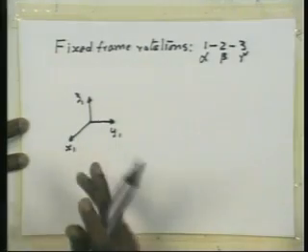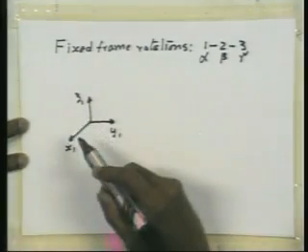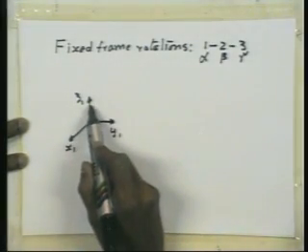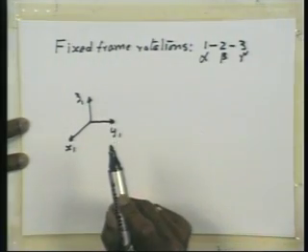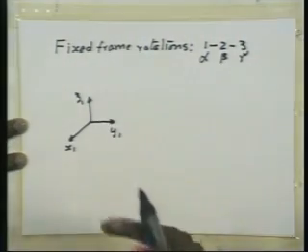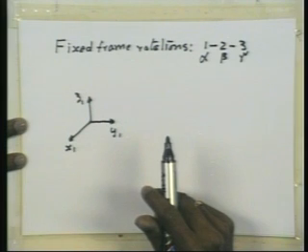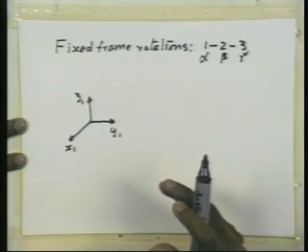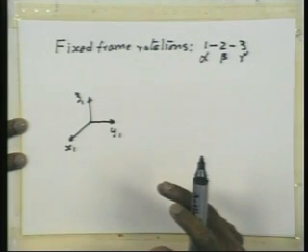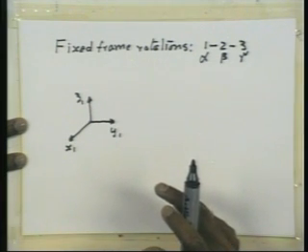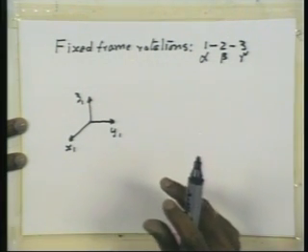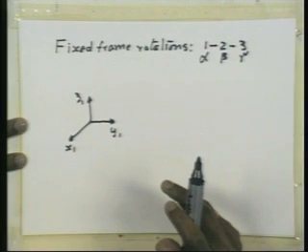So if we do that, the body z-axis rotates in this direction, y-axis in this direction by alpha in order to give you the new position of the body. Now instead of doing that, I am going to rotate the fixed reference frame with respect to the body reference frame by angle minus alpha about the x-axis, right?